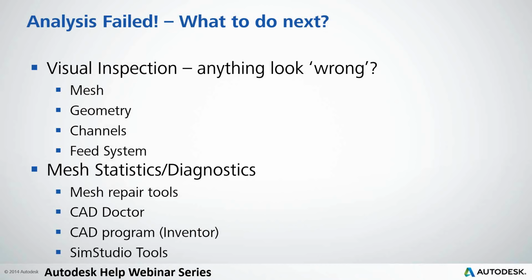Now, one thing to throw out there, if you do see a blank log after an analysis fails, Moldflow takes a little while to analyze the mesh prior to actually writing that log.